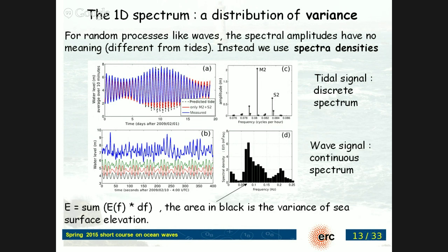So we take the time series, chop it up in blocks, and average the spectra together, and that gives us a chi-square distribution with n degrees of freedom. As n goes to infinity, your spectral density becomes very accurate. But of course, to average an infinite number of records, you need to record for an infinitely long time, and you have this uncertainty between the accuracy you have on the spectrum and the time resolution you have in your changing spectrum.